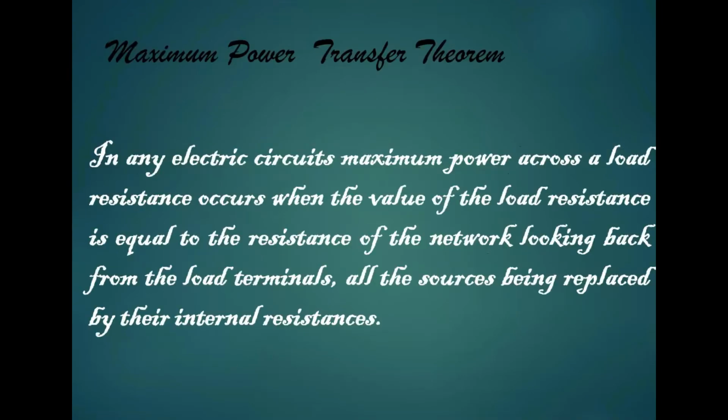The maximum power transfer theorem states that in any electric circuit, maximum power occurs across the load resistance when the value of the load resistor is equal to the resistance of the network, looking back from the load terminals, with all the sources being replaced by their internal resistance.